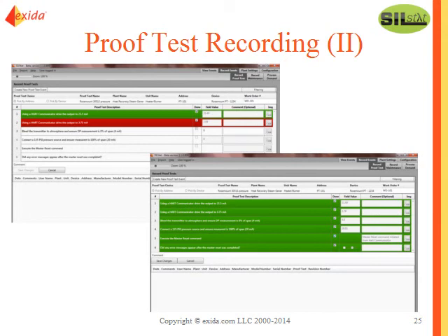So here we have an example. At the top, you'll see that for the 3.75 milliamps, we recorded a 3.89 milliamp value. Apparently, that's outside of the range. So it's immediately flagged as, hey, this proof test failed, this step failed, something is wrong here. You've lost some accuracy in your transmitter. In the example below, we've recorded 3.78, which is apparently within the range, the tolerance that we specified. So in that case, you see everything passed, everything is happy.